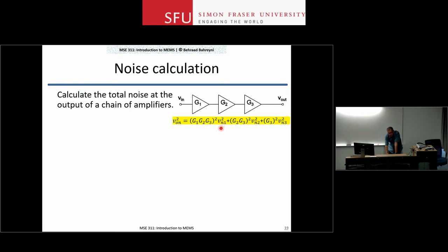If you want to have a low noise amplifier, go and make this as small as possible, because whatever that noise is, it is multiplied by the gain of the entire chain. The second stage has less gain, right? So 10 times less, 20 times less than the first stage. And that is usually a huge relieving factor.